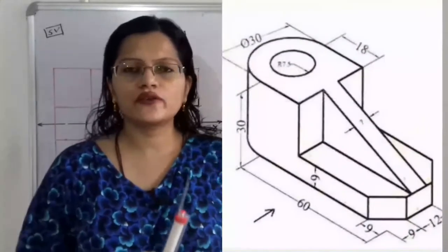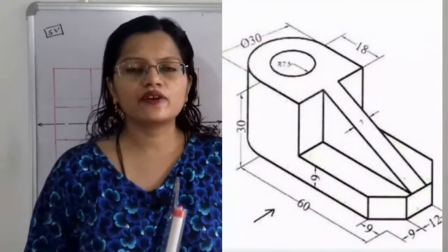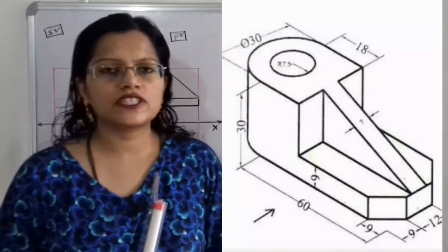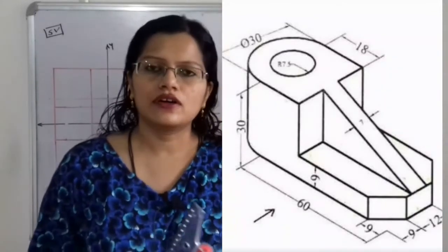Now this front view is getting completed. Now we will move to the top view. Before moving to the top view, we first have to complete the projections in the vertically downward direction from the front view to the top view.